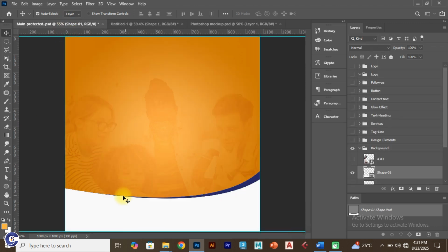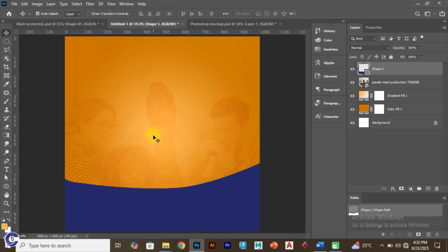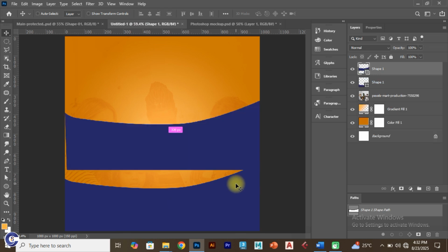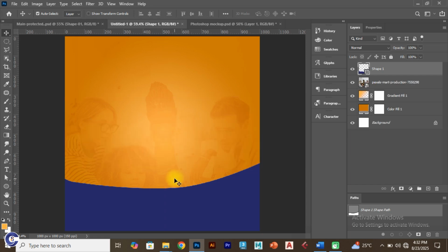So next thing we'll do, we have this white here, right? So you have two options. You could draw this white again from scratch. I don't want to do that. Okay, what I prefer to do is let's say I could just duplicate this. All right, to be on the safer side, when you're duplicating things like this, I want to place in place, because if I do Ctrl C, Ctrl V, it places it anywhere. So I will do, watch this. This is a layer that's active, right? Ctrl C, Ctrl Shift V. So it's duplicated, it placed in place, or Ctrl J directly. Okay, that's another option. You could just hit your Ctrl J, it just duplicates. It's a shortcut for place in place, right?